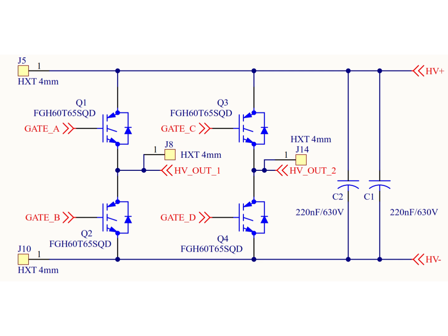Their role is to absorb high-frequency switching currents, reduce voltage overshoot caused by stray inductance, and keep the DC bus impedance low during fast switching transitions. Now let us look at the IGBT selection, which is a critical design decision in any high-power inverter.